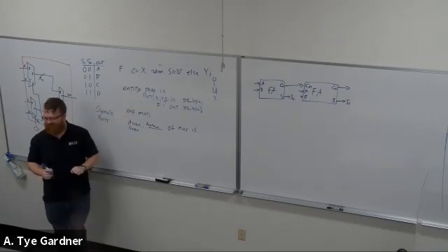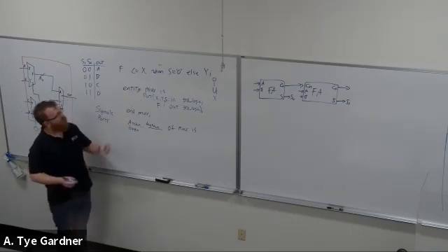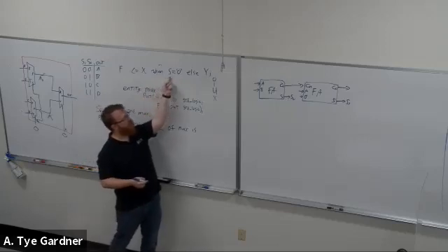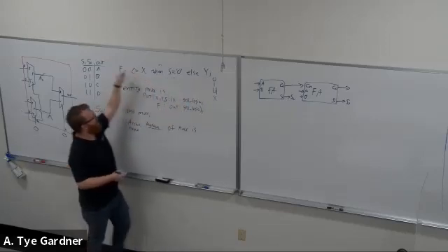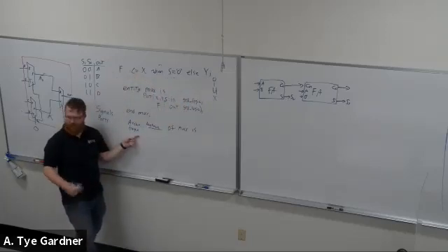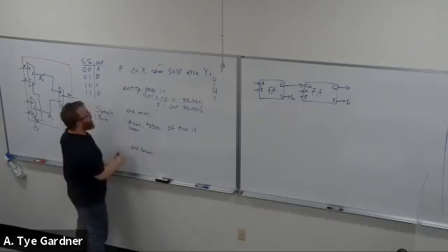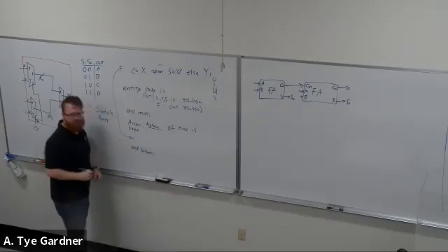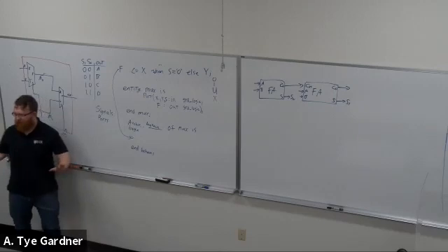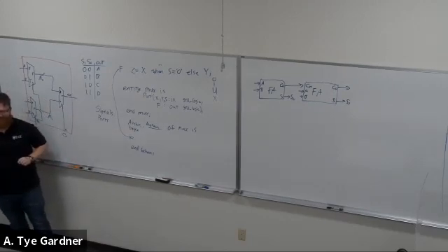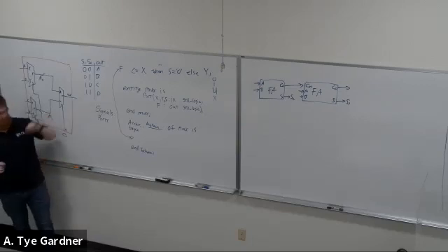I have X, Y, and S that are inputs. This X, this S, that Y, this code gets inserted in the begin. And then later I would say end behave to let it know that I am done. So this just plugs right into there. I now have a mux. Right? That's all. This is a mux.